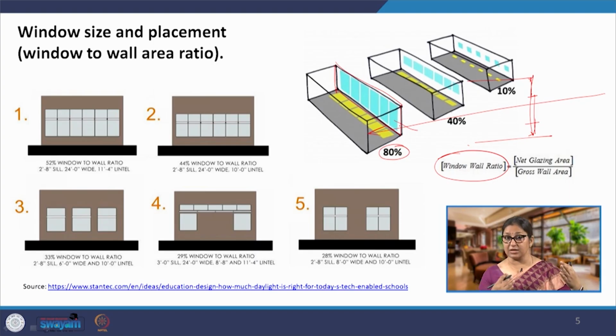So, the studio has to face east, so that the light coming from the northern facade does not cast shadow, and it facilitates. So, this is how careful we have to be when we design windows. Where do we place them? So, this is the second aspect of it. This is for daylighting that we are talking about. Ventilation, the placement, we have already covered in the previous lecture.